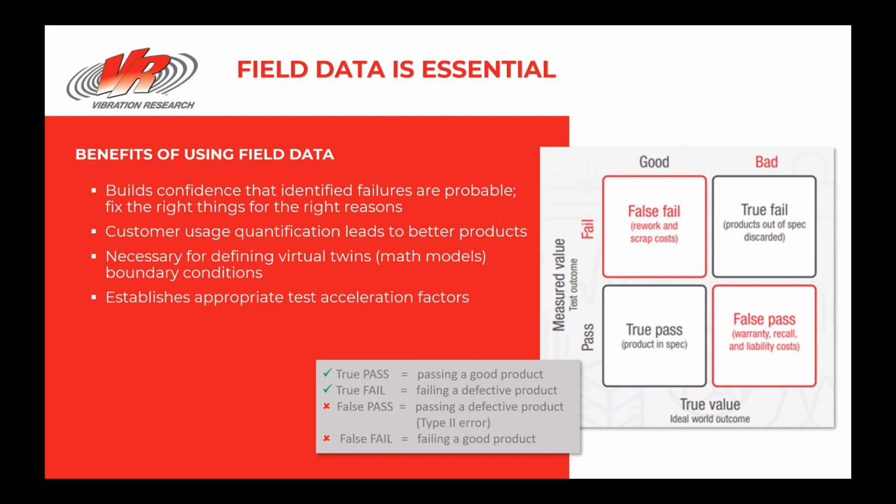Vibration test specifications are often written as success run, so that suppliers and OEMs can accurately predict test cost and timing. In a success run test, we know the length of the test, and unless there's a failure, we consider that it has met all the requirements. Although test to failure methodologies are more useful in many respects, even they must have correlation to end-use environment to yield meaningful results, and their durations are unknown, causing many scheduling problems in the product development big picture.